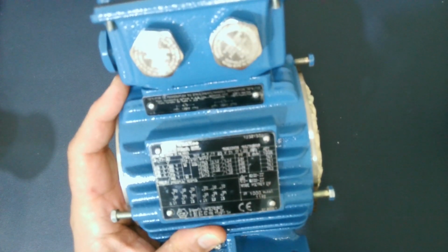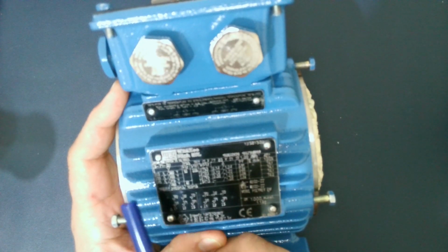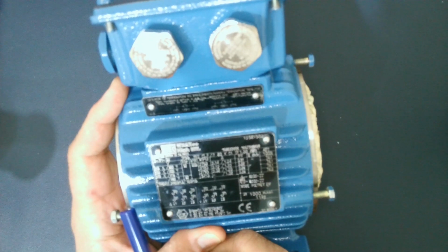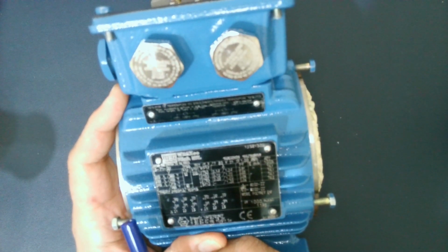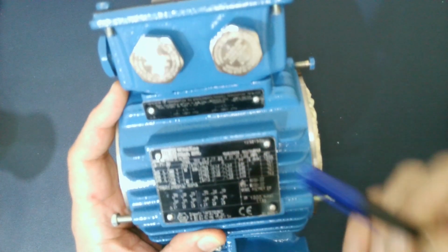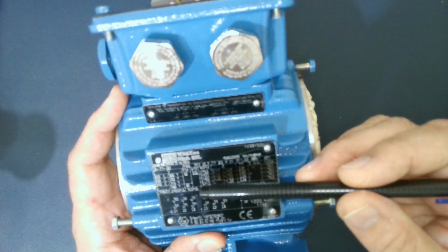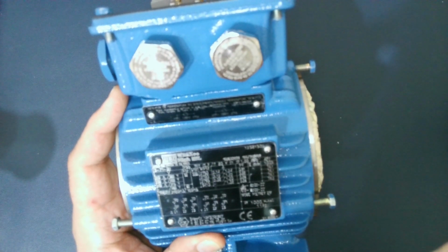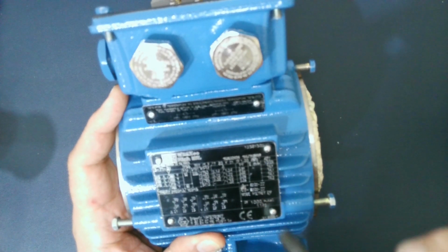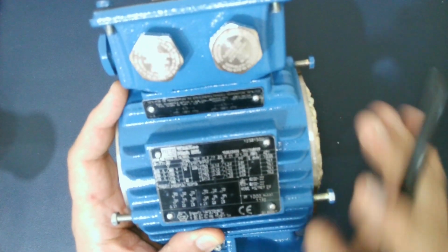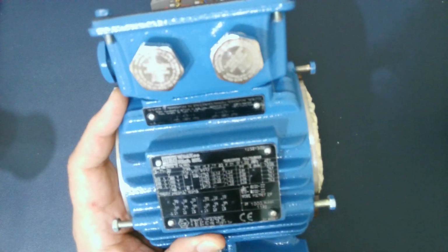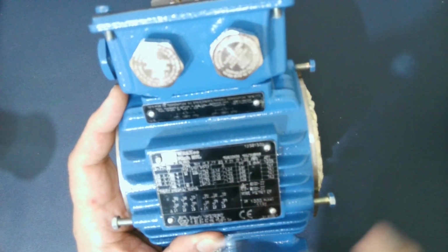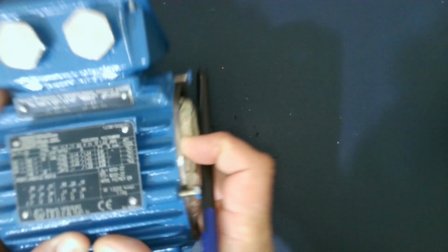So the nameplate tells us that this machine can be connected delta or star. So for delta 220 volt, for the star 380 volt, and the frequency is 50 hertz. And also you can have the power, which is 0.55 kilowatt, and the speed, which I need to know, 2750 RPM, and it gives you the currents. I'm not going through everything written here now, so we are going to discover that bit by bit, but now what I need is the speed. So we can make some calculations now.